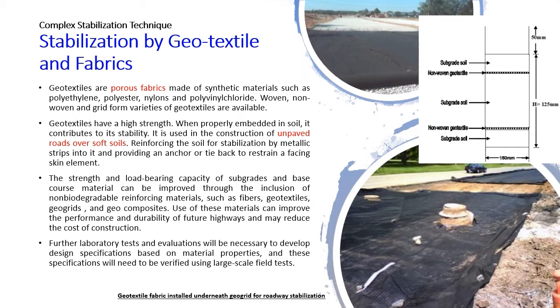The major functions of geosynthetic materials in relation to transportation engineering are separation, reinforcement, filtration, drainage, and acting as a liquid barrier. In providing filtration and drainage, it aids in improving subsurface drainage and allows the rapid dissipation of excess subgrade pore pressure caused by traffic loading. However, the geosynthetic must minimize the possibility of erosion of the drainage layer and resist clogging of the filter over the design life of the pavement.